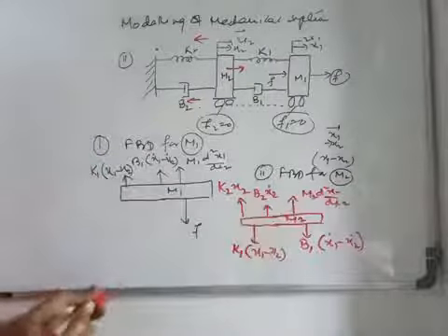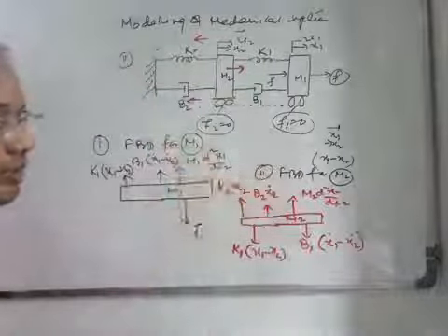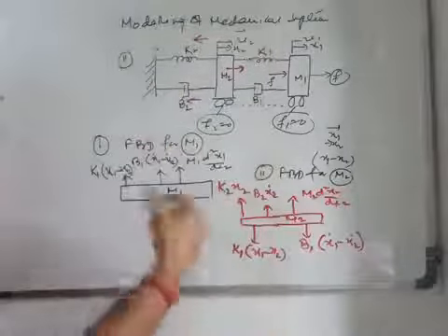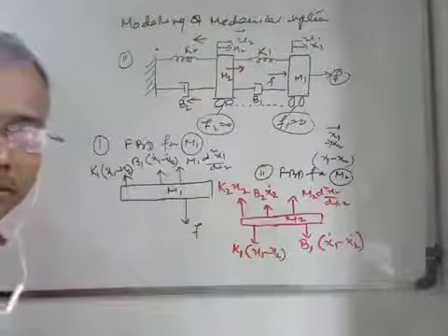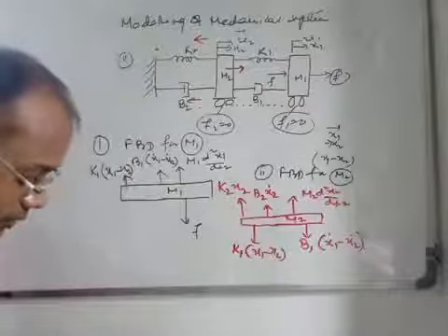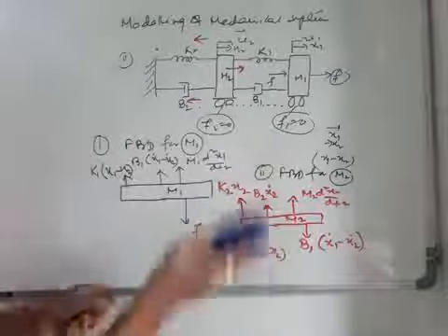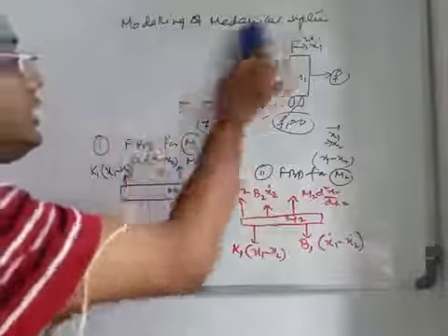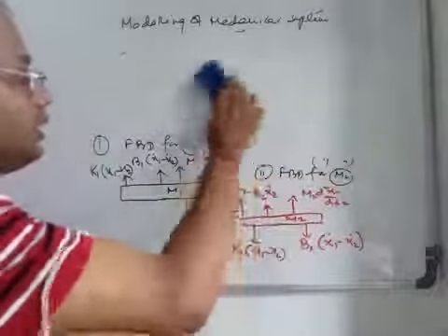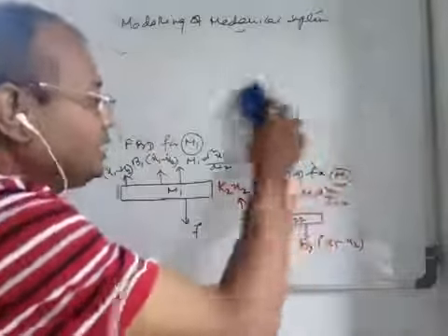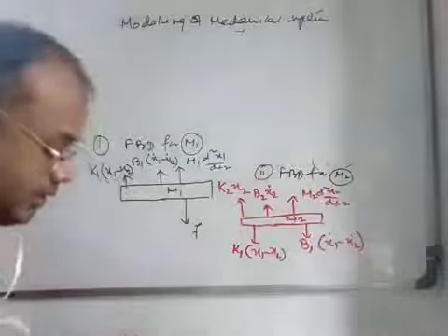Now once you see these two free body diagrams for this complete system, you get the differential equations corresponding to that, right? I will write the differential equations corresponding to the two free body diagrams, and that gives you the mathematical model for that two mass system in practical situations, right?